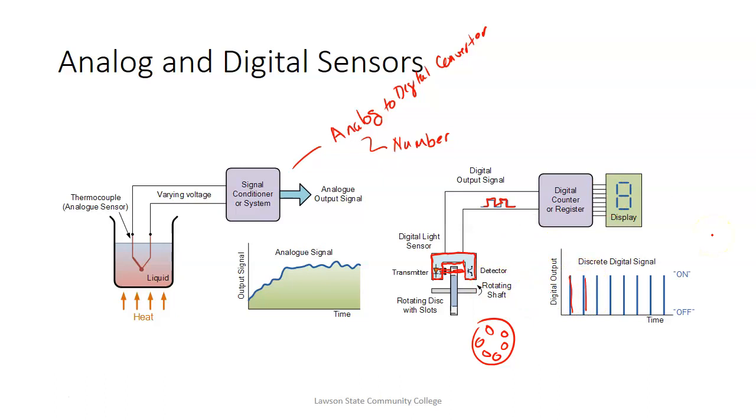If it was analog, I would get a voltage that represents speed. We do have those. Those are very, very predominant until we came out with these encoders, which are probably dominating speed now. But used to, we just ran a generator that the faster something ran, the more voltage it would put out. And then we'd use that. And those are still, you'll probably run into those a lot.